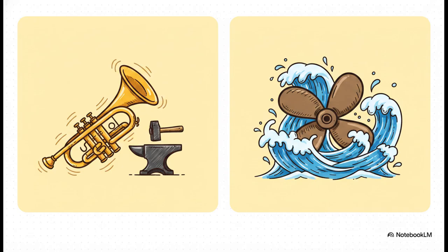Let's look at copper alloys, for instance, which are famous for their corrosion resistance and formability. Within this group, we can compare brasses against bronzes. Brasses use zinc as their primary alloying element. This creates a softer, highly ductile metal that is easily cold-worked, perfect for forming intricate musical instruments or stamping out cartridge casings. Bronzes, on the other hand, use elements like tin, aluminum, or silicon. This recipe yields a much stronger alloy with an even higher degree of corrosion resistance, specifically designed to survive and maintain its strength in much tougher, highly corrosive environments.